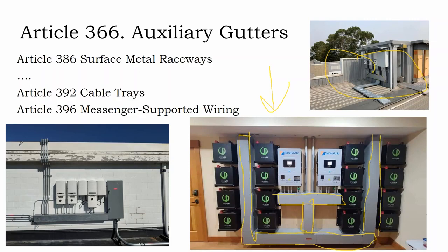And it depends on that DC wiring needing to be in metal. This is probably the DC side. If you wanted to be completely code compliant, maybe inside here you maintain some metal, or you make this particular box metal and have this be AC and have it be plastic, or these might be metal gutters.